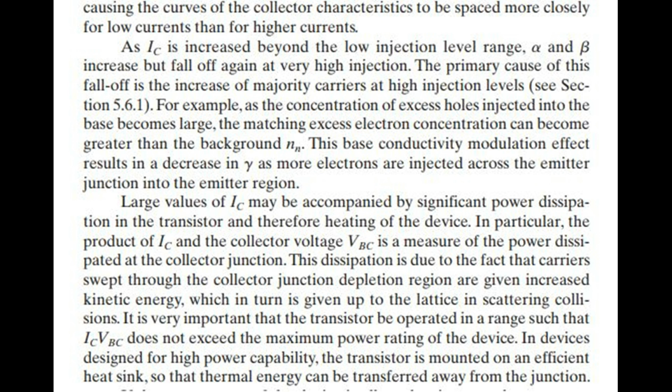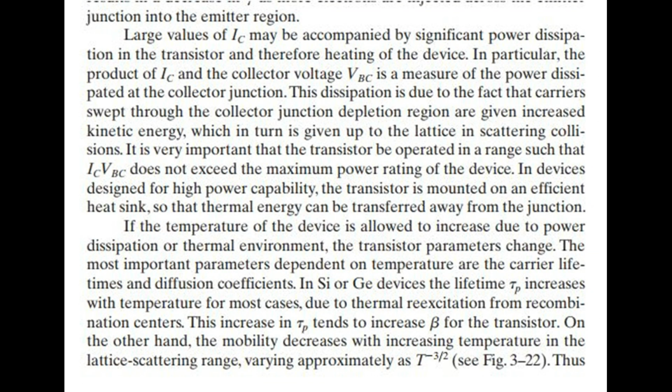In devices designed for high power capability, the transistor is mounted on an efficient heat sink, so that thermal energy can be transferred away from the junction. If the temperature of the device is allowed to increase due to power dissipation or thermal environment, the transistor parameters change. The most important parameters dependent on temperature are the carrier lifetimes and diffusion coefficients.